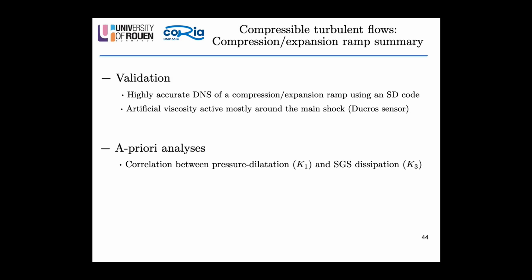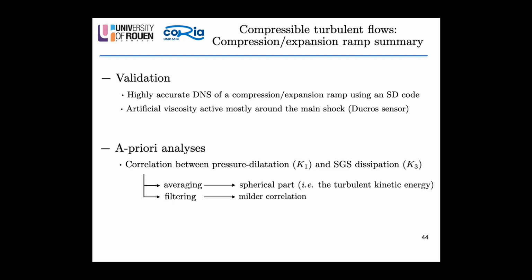We notice a correlation between pressure dilatation and SGS dissipation, which on average was only caused by the spherical part, so that the deviatoric part instead was not correlated, whereas in the filtering sense there was still some mild correlation between these two terms.